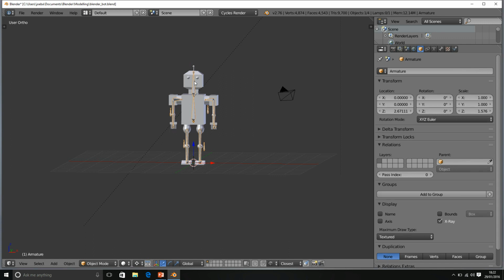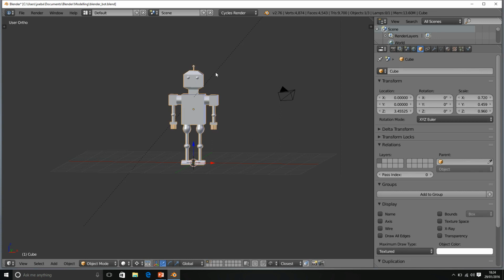What we're going to do here actually is just move these to another plane. So we're going to press M and move here, and if we check on, we can see that our entire rig is on the second layer, which is good because we don't need it visible at the moment. So now we've got our Blender bot, we've got it at a good size.